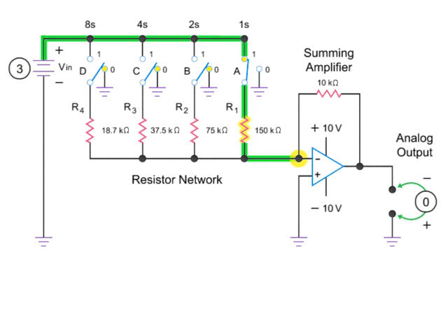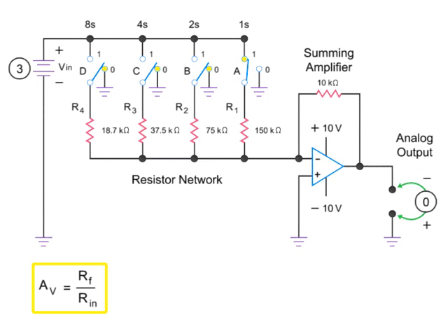The process of determining the magnitude of the analog output signal from the voltage input of the resistor network requires calculating the gain supplied by the amplifier. Gain can be calculated by dividing the resistance at the feedback resistor by the input resistance. With this 4-resistor arrangement, input resistance will vary in switches A, B, C, and D based on the kiloohm value.